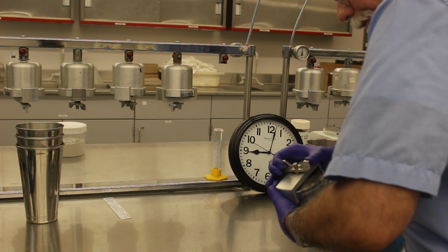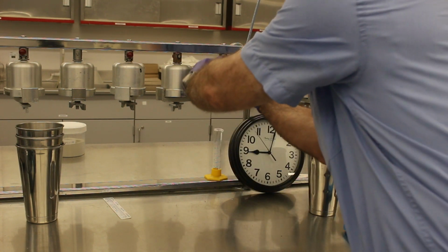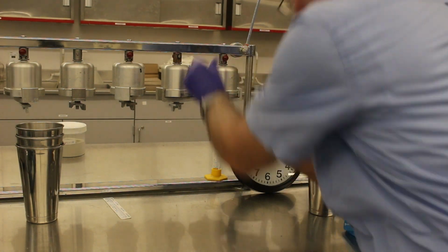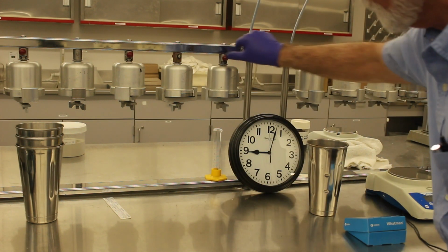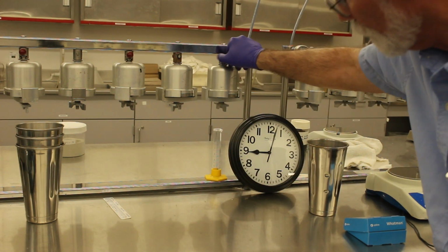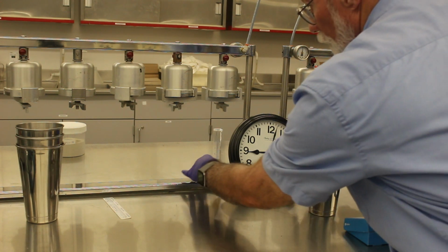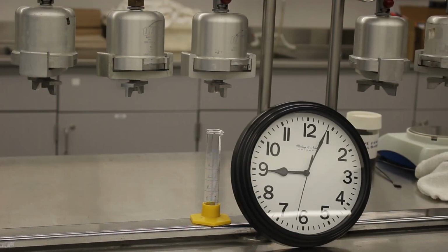Then place the dry graduated cylinder under the drain tube to receive the filtrate, close the relief valve, and adjust the regulator so that the pressure equals 100 plus or minus 5 pounds per square inch. At the end of 30 minutes, measure the volume of filtrate. Shut off the flow through the pressure regulator and open the relief valve carefully. It may be desirable to use a 1-hour filtrate test for oil-based muds. The time interval, if other than 30 minutes, shall be reported.